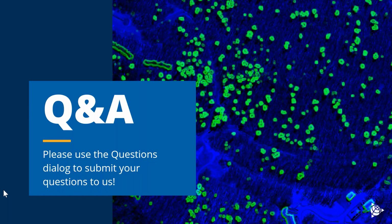You could use this methodology to detect not only trees, but rock outcroppings, landforms, and major disturbances within the forest. If you made a DEM surface, took a hillshade of that and used it as an input, you could use a segmentation algorithm to capture that disturbance area, say a landslide, map that out, and go from there.